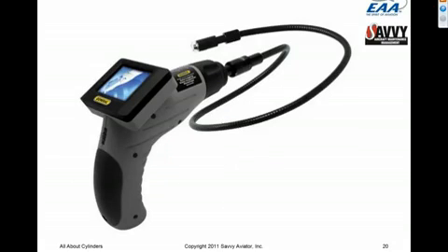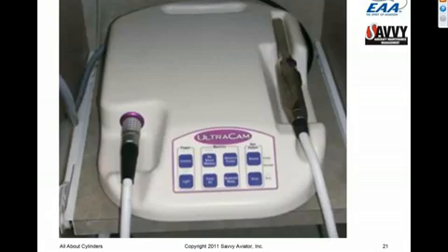Here's another example of an electronic videoscope that has a little camera at the end of this probe. This is actually the borescope that I use. It's not designed as a borescope at all. It's actually a dental intraoral camera designed to take pictures of patients' teeth in a dental office, but it happens to be a superb borescope. It fits into the spark plug hole very nicely, and it creates just absolutely wonderful images. And I'll show you some of those images in a minute. But this is what I use for borescopy in my hangar. Here's some pictures.